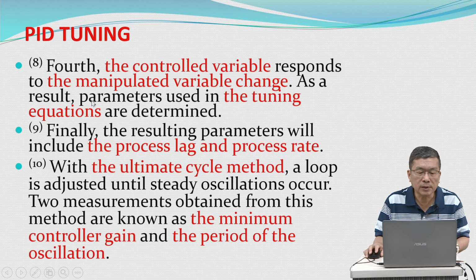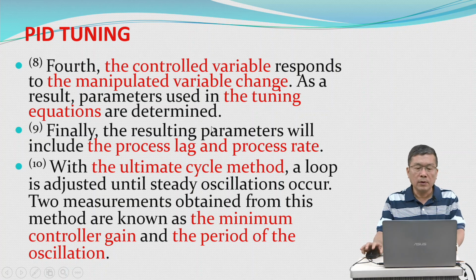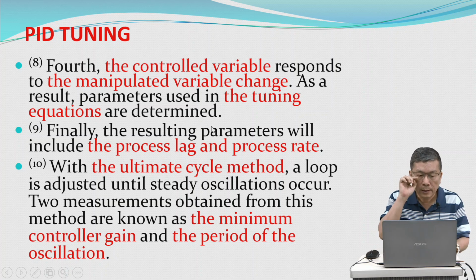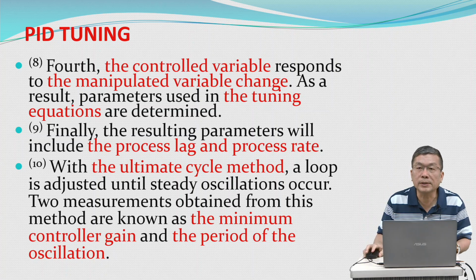As a result, parameters used in tuning equations are determined. Finally, the resulting parameters will include the process lag and the process rate.